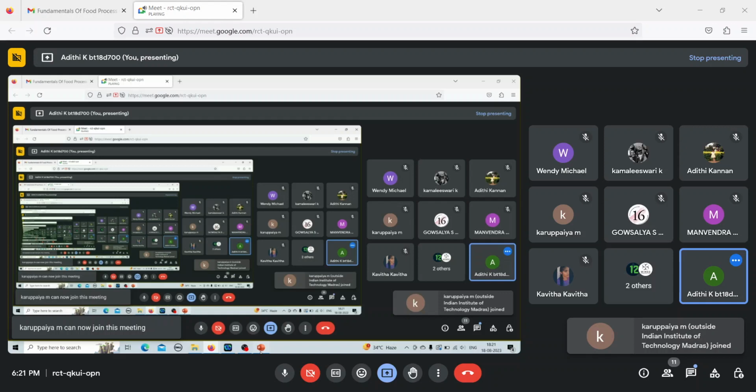I am converting it into kg per second, so I am dividing it by 3600. So 132 by 3600, Cpf is 3.9 kilojoule per kg, and Tf is basically the temperature at which you are sending in the feed. It was given that the feed is already at its boiling temperature, which is 323 Kelvin. So I am substituting Tf as 323 minus 273, equal to L, we found out 40.615, again converting it into kg per second. So 40.615 divided by 3600.